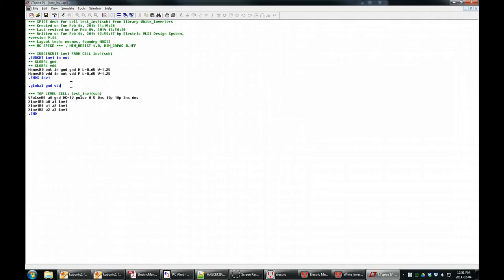Those nodes are everywhere. If we name them anywhere, they're connected. Global variables usually are a bad idea. Sometimes, especially for a digital part like what we're doing, those two nodes actually do go everywhere. If this is an analog design, I would take off points for having global nodes because it's an invitation for trouble. Digital stuff for this is okay.